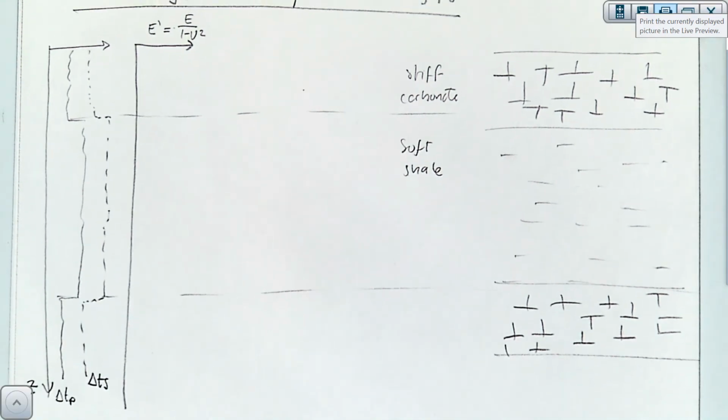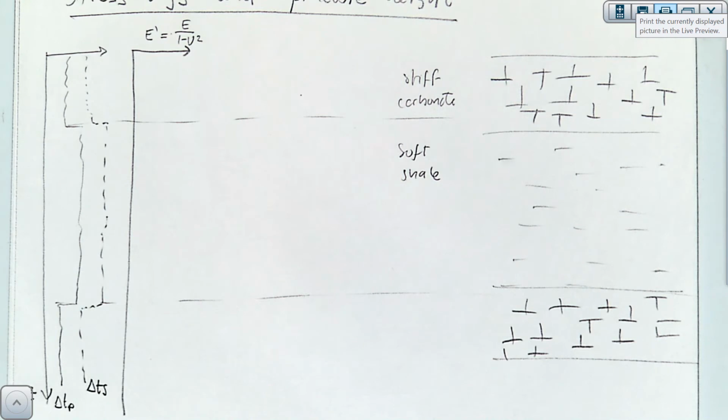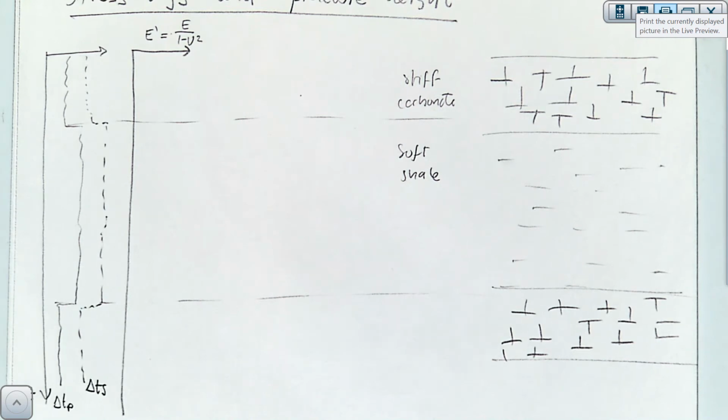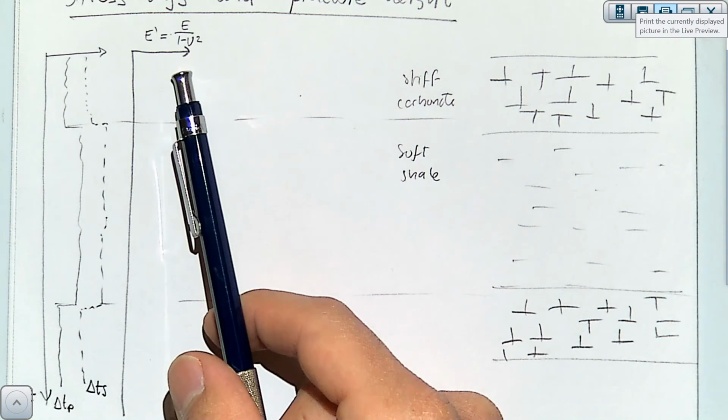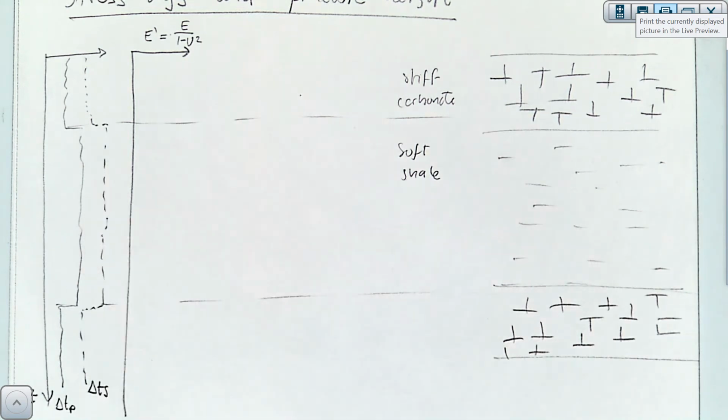Usually in subsurface applications, we almost never use just the Young modulus by itself. It's always combined with the Poisson ratio because it's under a state of loading which is not just in one direction and unconfined in the other one, but it is confined in the other two. And I'll explain why we have this plane strain modulus in a bit. But this is just telling you how stiff the rock is.